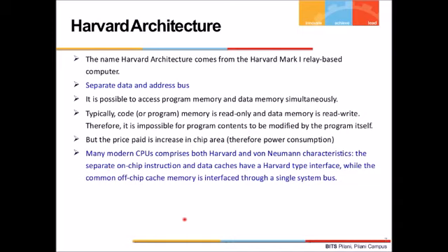Okay. So nowadays, the common practice of designing a CPU is that the internal data and instruction memories follow Harvard architecture. That means separate data and separate instruction. Whereas there is another memory which is external to the CPU, which is accessed through a von Neumann architecture. Okay. So basically there are cache memories. We'll discuss cache memory later. So internal cache is based on Harvard. The external cache and external memory is based on von Neumann. Okay. Hope now it is clear.